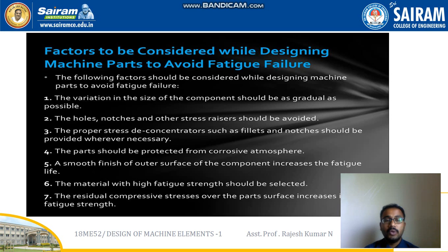Next, holes, notches and other stress raisers should be avoided. Indirectly this means the stress concentration factor, all the stress raisers should be avoided. Proper stress deconcentrators such as fillets should be provided wherever necessary. We also need to make sure there are no sharp corners or edges, and that proper fillets and smooth surfacing are provided, to avoid the fatigue failure.